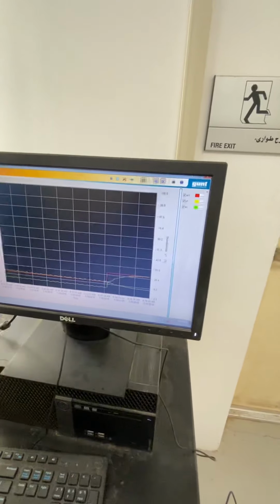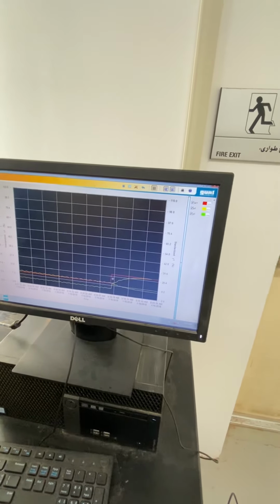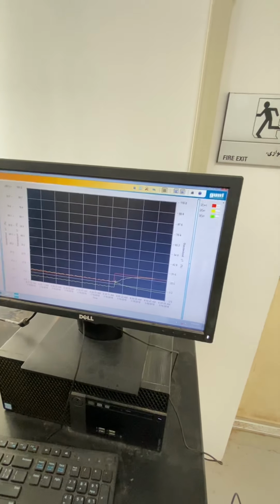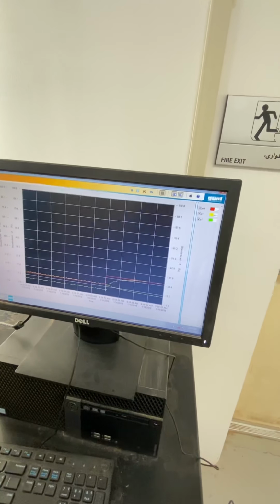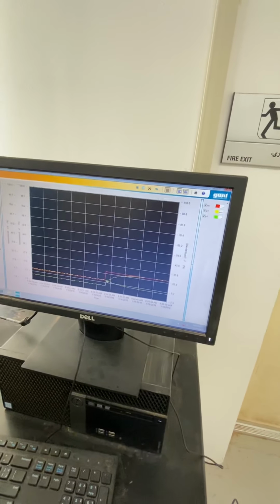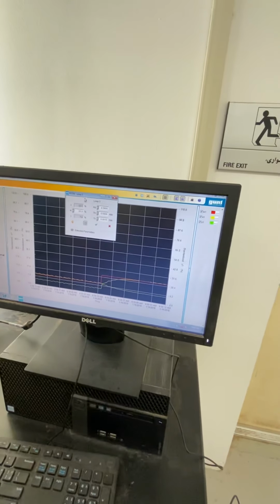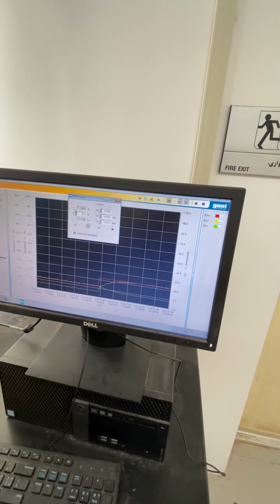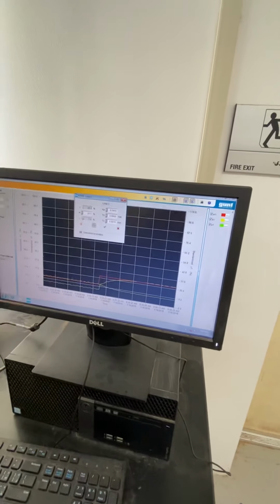And so as you can see right now, once I change the set point to 20%, the automatic controller started to calculate the error, which is the current measured value with the set point. It is a negative error. So you can see for the inverse action, with the negative error, the output signal will start to increase. Okay guys, so as you can see right now, the process value is at 20%, almost matching with the set point, and the output signal from the controller is at 7%.